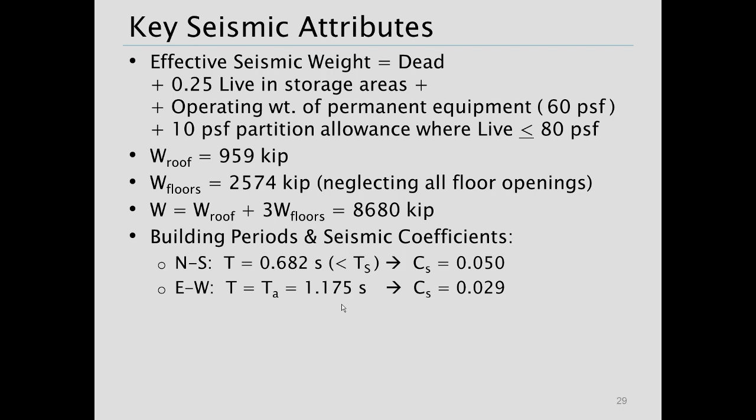So I'm going to go with that, and that's 1.175 seconds. Now, of course, our period estimate can often be a critical thing in terms of refining and getting the loads that we actually want to design for or need to design the building for. Other things, building site class could be an important thing here. We basically assumed site class, or I assumed site class category B, in coming up with the seismic loads.